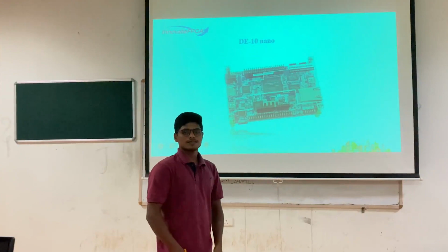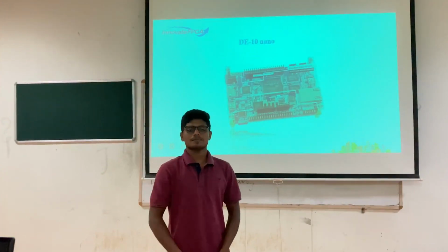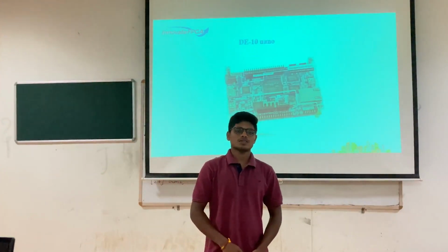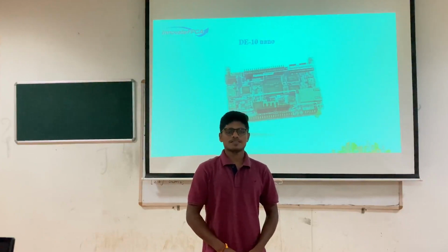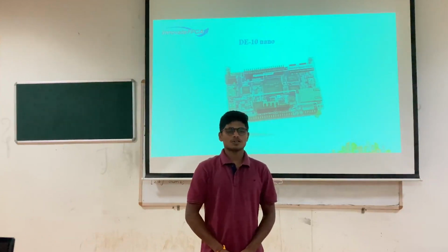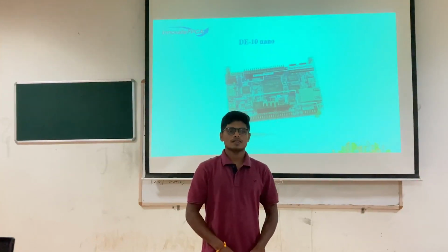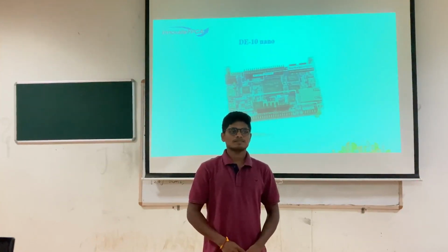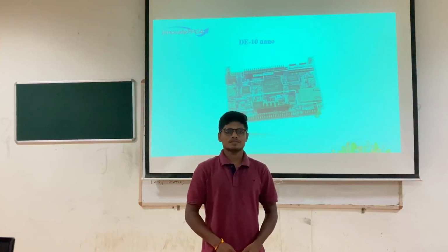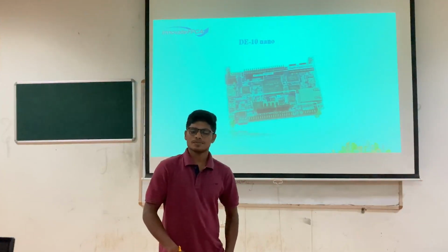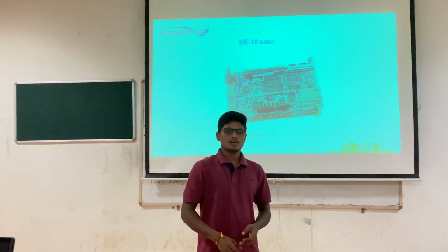The DE10 Nano board consists of 2 parts, the HPS part and the FPGA part. The FPGA part is controlled using Verilog, whereas the HPS part has an operating system. In our project, the complete processing and GPU access is done using the HPS part. To use the board switches, we need to access GPIO pins from the HPS side, which had a computer vision supported operating system.